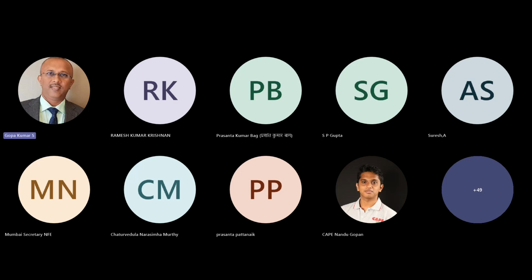So the entire wording, as you rightly said, neutral earthing has been changed to system reference earthing, and the neutral earth conductor can be called the system referencing conductor. These changes happened because of the implementation of the smart grid, the PEI, and so on. Over to you, sir.